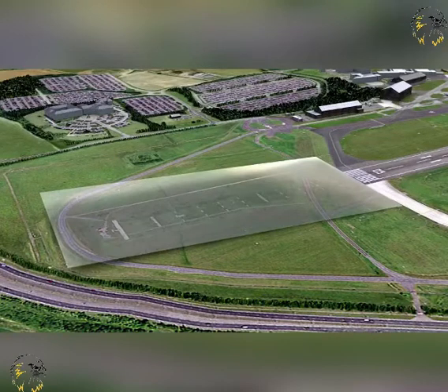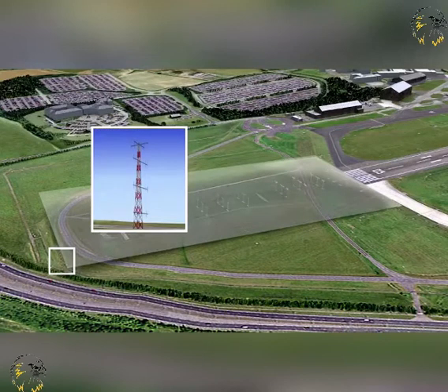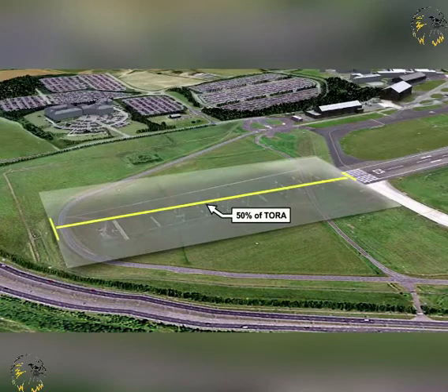The clearway is actually the area underneath the clearway plane. The clearway plane extends from the end of the runway with an upward slope not exceeding 1.25%, above which no object or terrain protrudes. The length of a clearway will be the lesser of the following 2 distances. The distance to the first upstanding non-frangible obstacle, or frangible objects of 0.9 meters or more in height, or a distance equivalent to 50% of the takeoff run available, which is a distance that we will define shortly.